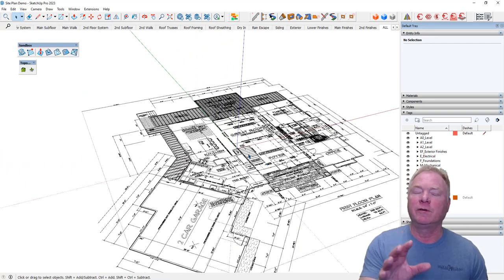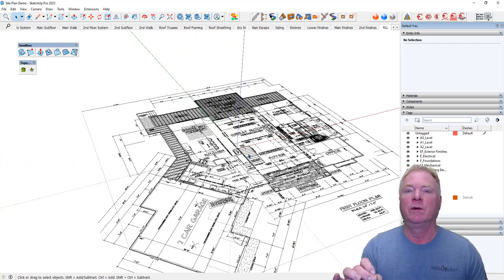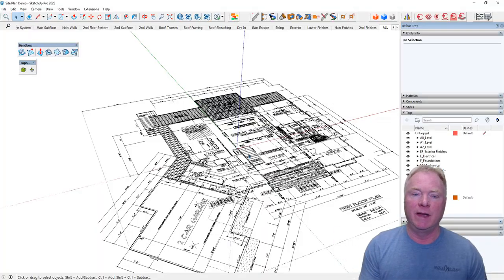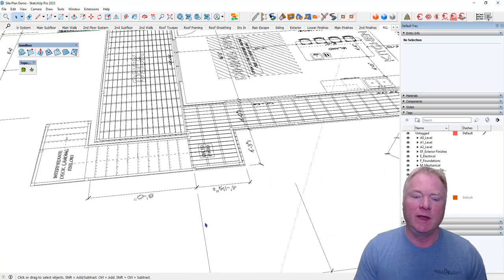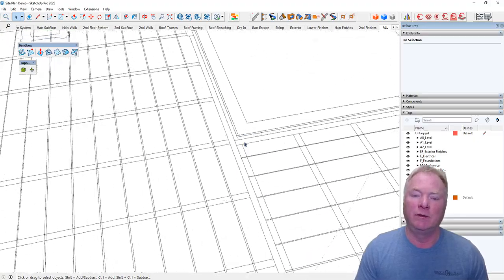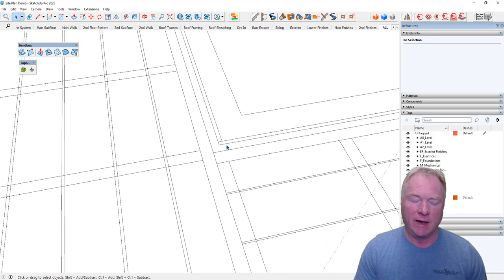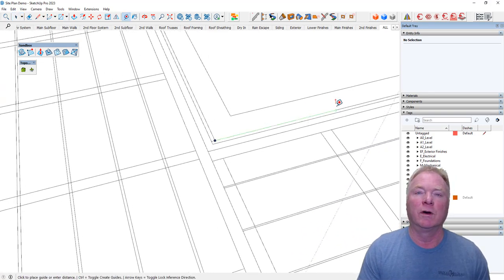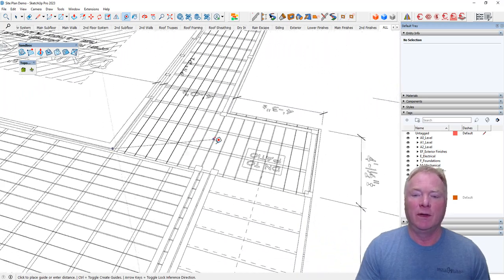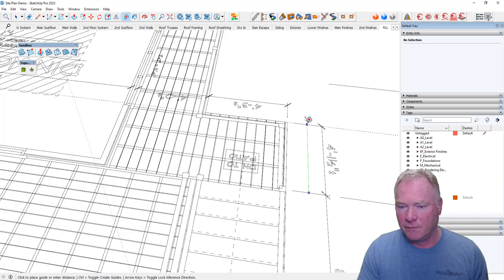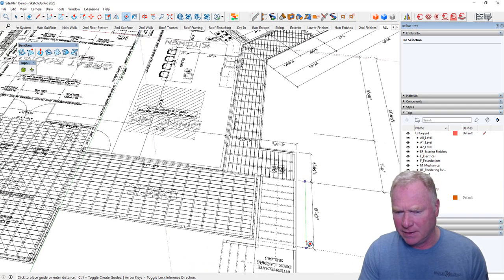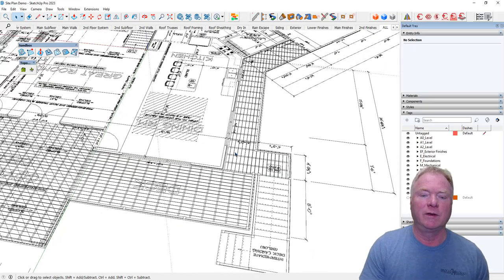Now what I'm going to do first is find a common corner to the next plan, the basement plan. This is a walkout basement, and in this case they dimension to framing. I normally go to sheathing, but right now they've got a dimension to framing, so that's what we're going to use as our reference point, this outside corner of framing. Okay, let me take that back. I need to verify my scale real quick. That says 4 foot 1 and 5/8. Let's see if this will be 8 feet, and we're at 8 feet, so we're good to scale.